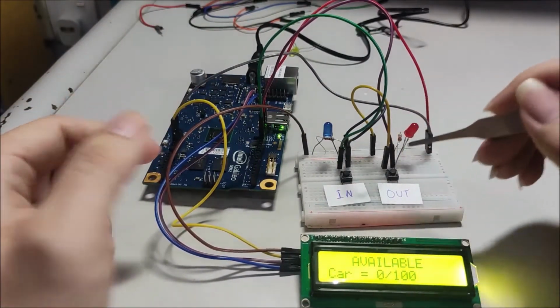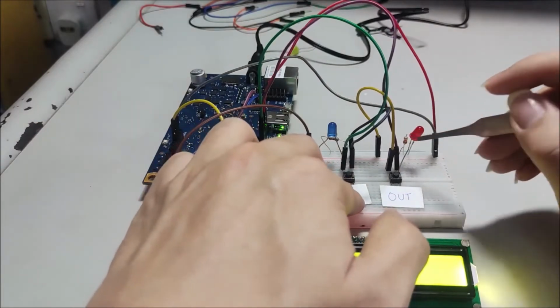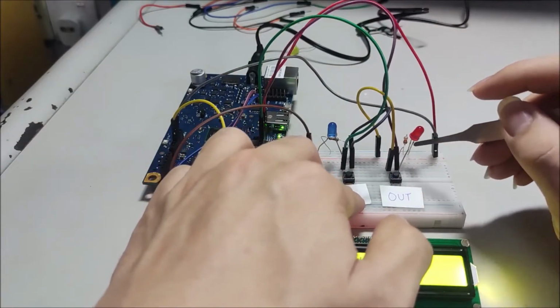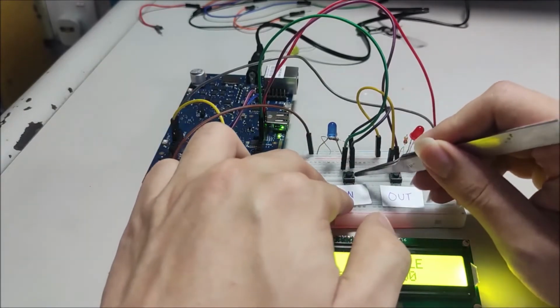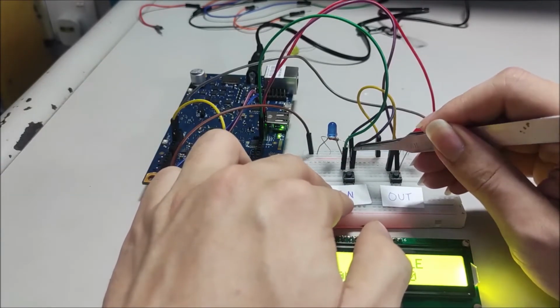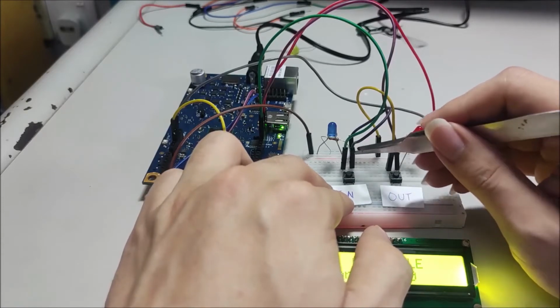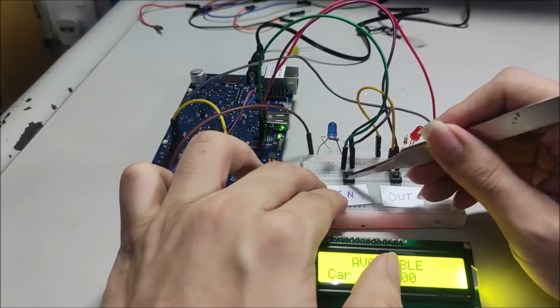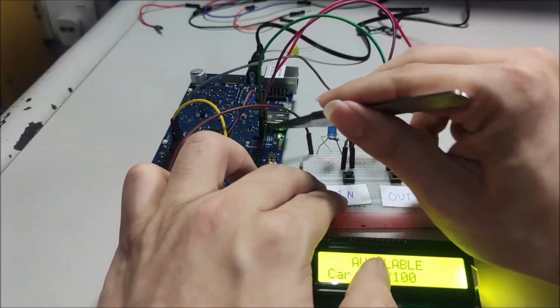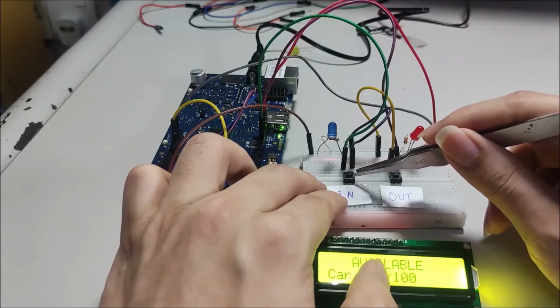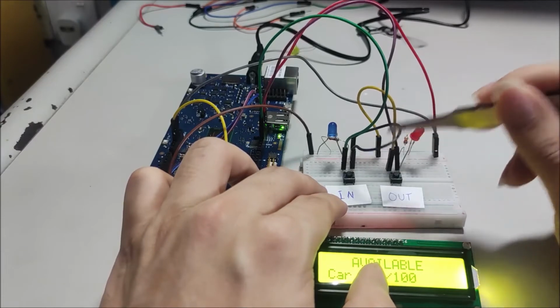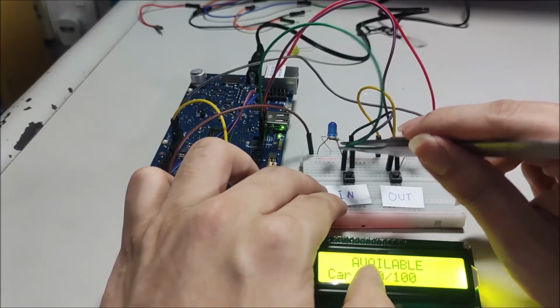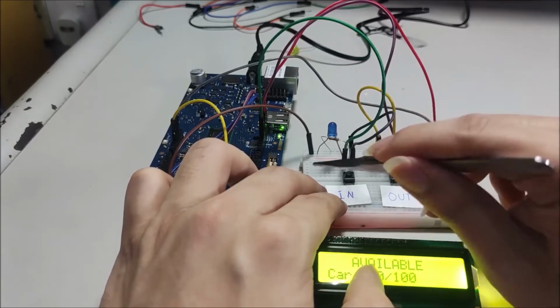This condition applies to pin 13 as well, which is also connected to the red LED and a resistor. For the other side of the button, we connected it to the VCC 3.3 volt, so that when we press the button, pin 12 will receive 3.3 volt, which is a value of 1, and once we release the button, it connects back to ground.